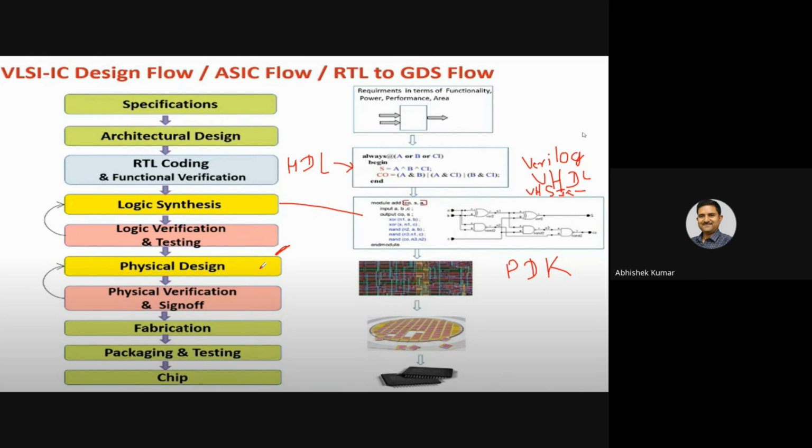It's mostly known as physical design. In the physical design, the diagram which I have shown, here it is going to discuss every synthesized circuit. Here we have a layout map, that is called layout, or we can go for connections, transistor-driven diagrams. Here we will discuss RLC, parasitics, all the analog electronics to be discussed during this simulation. Finally, we can go for one physical sign-off. Here we will discuss one topic called timing analysis, the STA part, and fabrication.